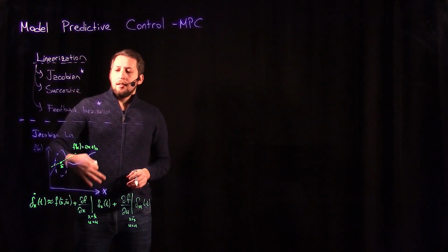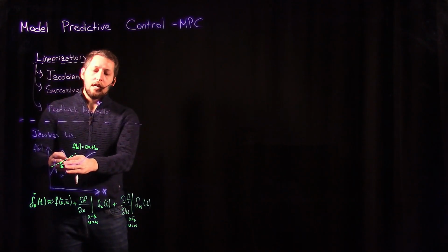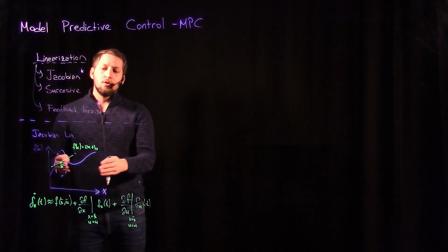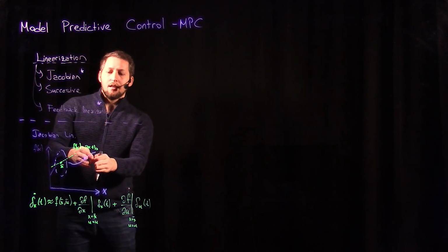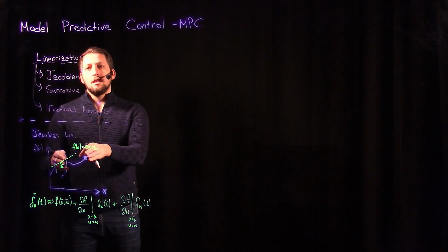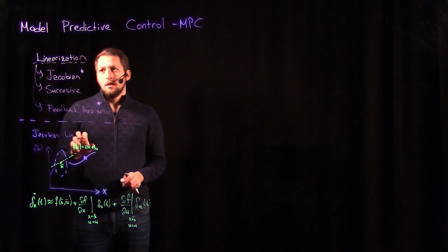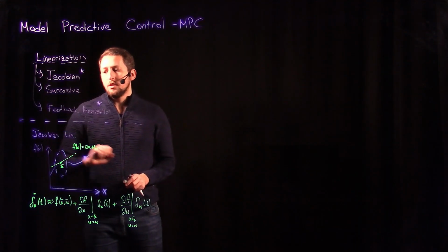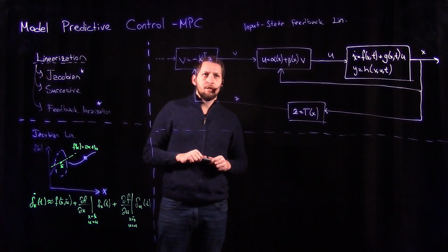So this gives you a linearized system model at the end of the day, but you should be careful because, for example, if your actual working points increase, or you have larger perturbations in your system, for example, you hit somewhere over here, the system's dynamics at this point and the actual linearized model are behaving totally different. It's because if you are really working around a working point or equilibrium point, this can work fine, but what I'm trying to say is that you should be really careful when you are using this Jacobian linearization.